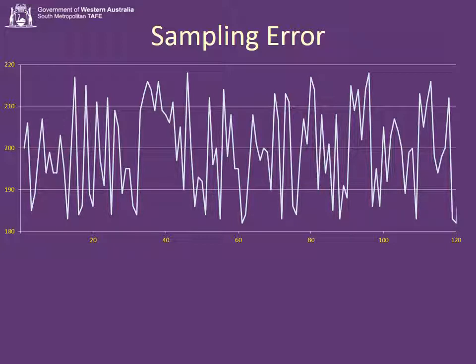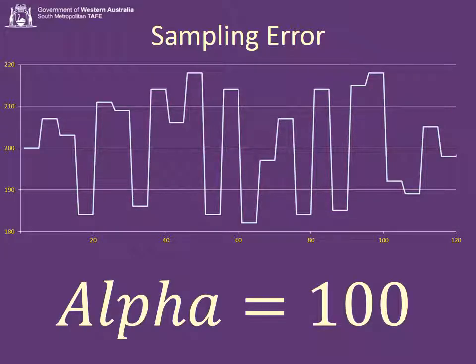The control just will be rubbish. It will be constantly hunting. So we need to filter it. Firstly, let's have a look. The ADC samples it, and with an alpha of 100, it looks like that. That's still not good. The BMS cannot control with that sort of a signal. It'll be trying to correct what's not really there. So we use the alpha.